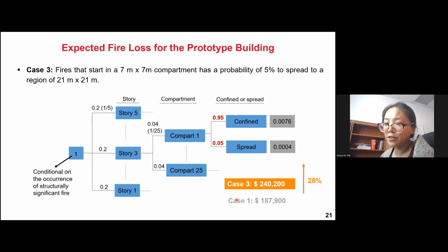That's why in the structural design or in the fire safety design, there are a lot of firewalls. Those firewalls are trying to make sure that when the fire happens in one area of the building, they can prevent the fire from spreading to the other side of the building. And there's also a fire resistant floor system, and those floor systems are trying to make sure that if the fire happens in one story, it does not spread to the other stories.